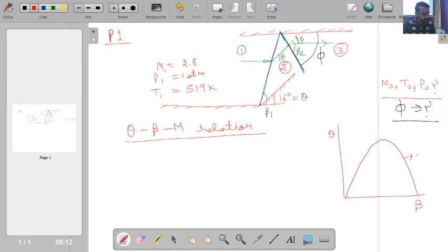Say this corresponds to Mach number 1, and I now have the value of theta as 16 degrees. So corresponding to this 16 degrees I will get two values of beta from here. And as I told you earlier, unless there is a very high back pressure, we will not have the presence of strong shock waves. So there are high chances that weak shock waves will always be favored. So corresponding to the weak shock wave, this particular value is my value of beta 1.